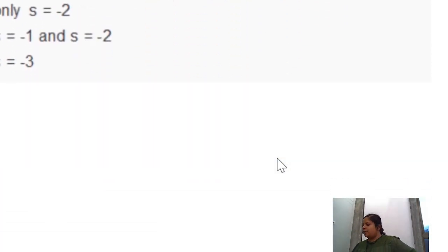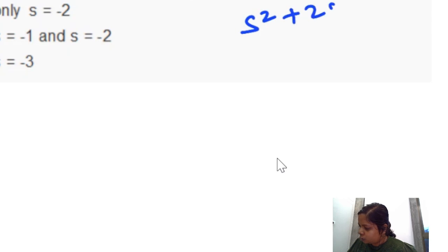Okay. The complex function, this is singular at what value? Singular at what value means basically at what value of s you are going to have the response explode to infinity. So it basically means at what value of s this whole term is going to be 0.